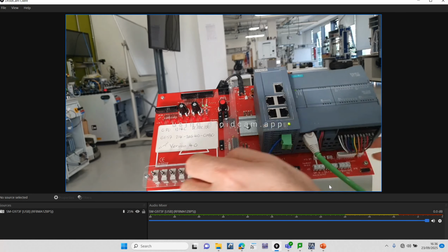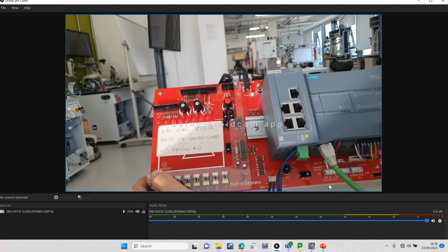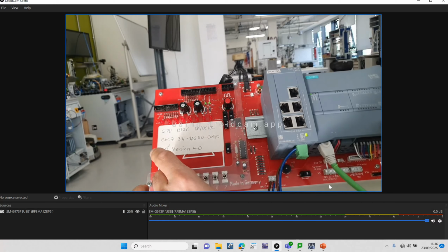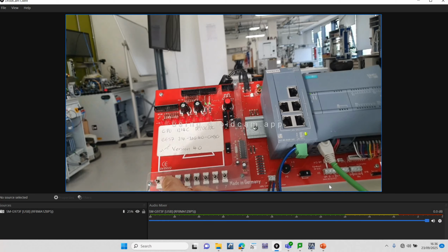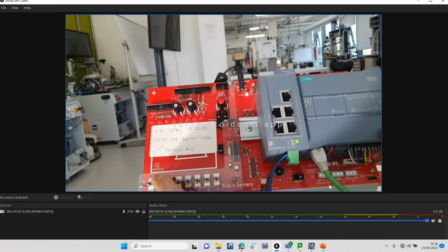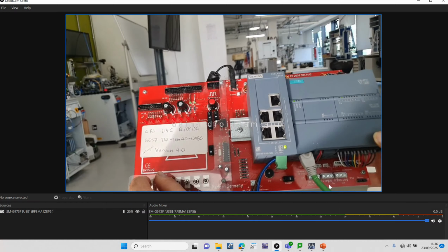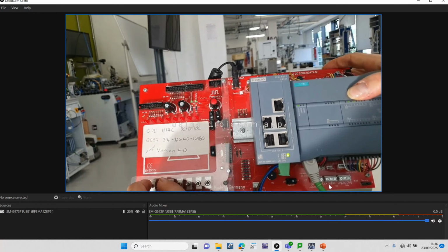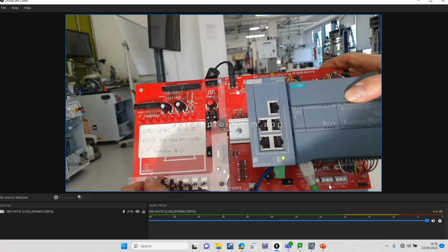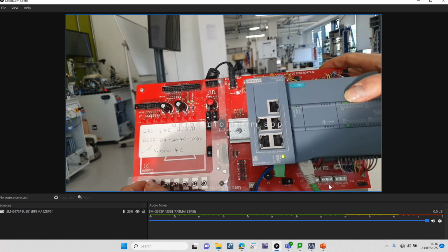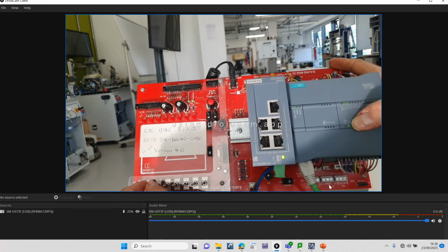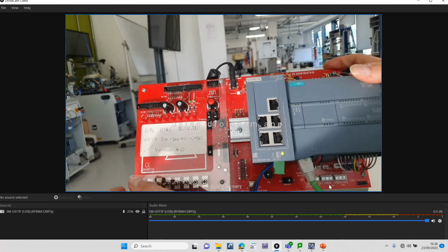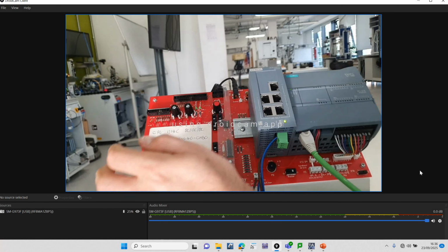So now if I activate switch number 1, which is I0.1, the second switch, the LED turns on. And as soon as I turn the second switch on, you can see the output Q0.1 turns on. And now we are going to test it in the program.